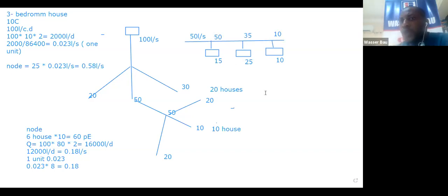That's how it goes. So it means that when this 50 liters per second gets here, the house connection, the number of houses in the layout, the population density here takes a value of, say, 15. What is left will be 35 that will service 2 other districts or estates. And those 2 other estates are having, I don't want to say number, but I want to say a weight. It's carrying a weight of 10, and this one is carrying a weight of 25.